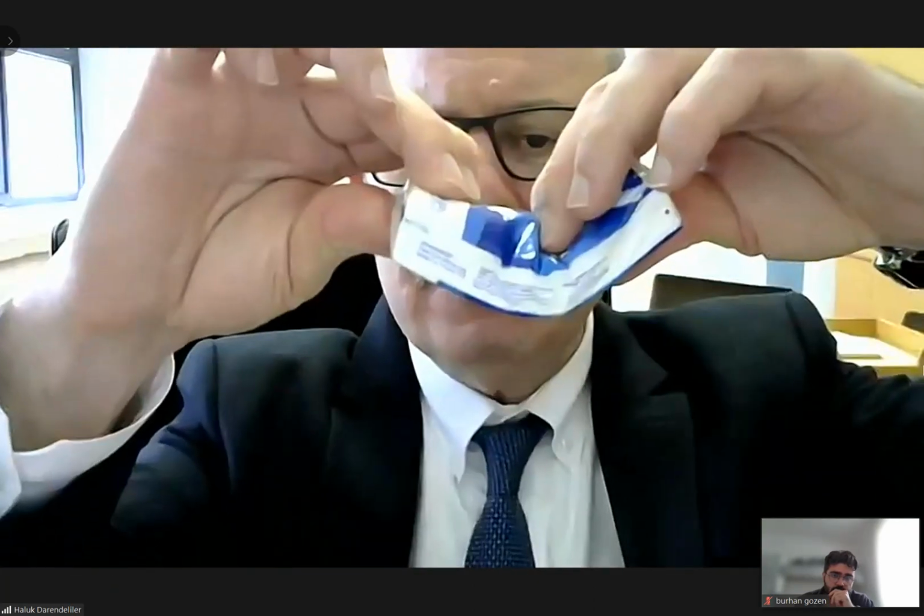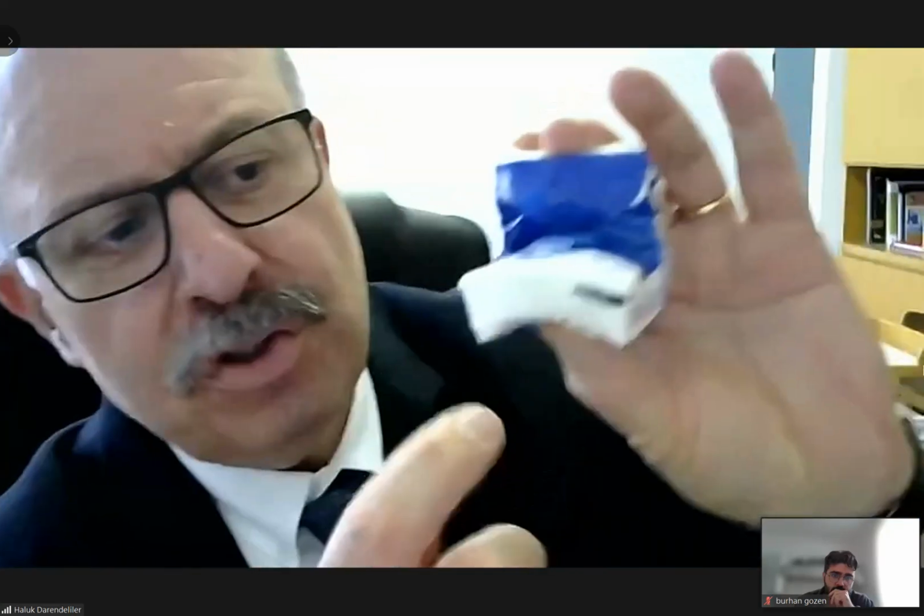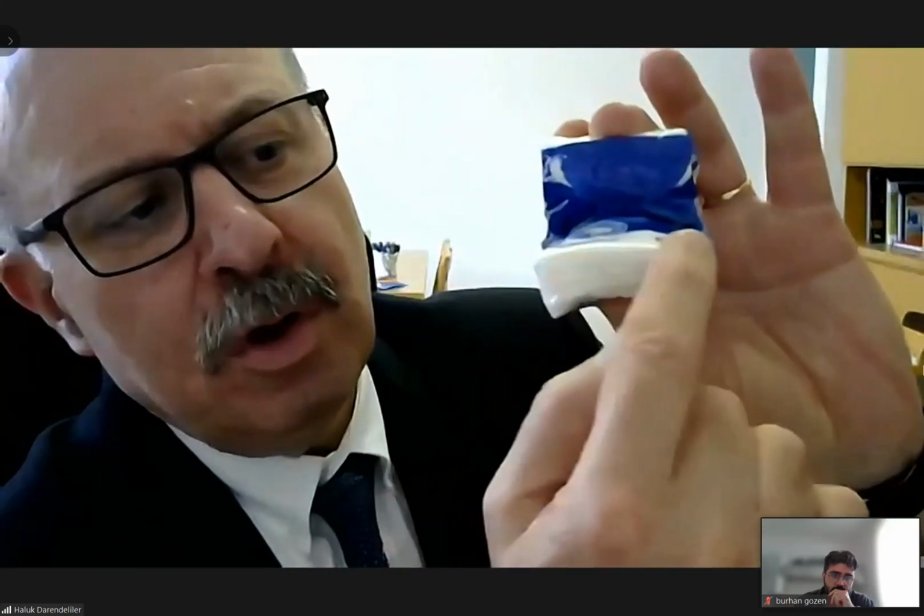Now, I'm not talking about this by anticlastic curvature. Anticlastic curvature is this. When I bend this like that, on the cross section, this portion, because of compression, increases in length. The lower portion decreases in length. So this rectangle now is not a rectangle anymore. And then these two define a new radius of curvature.